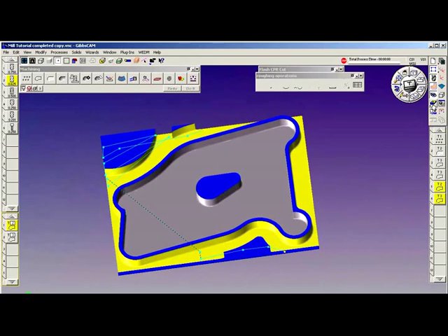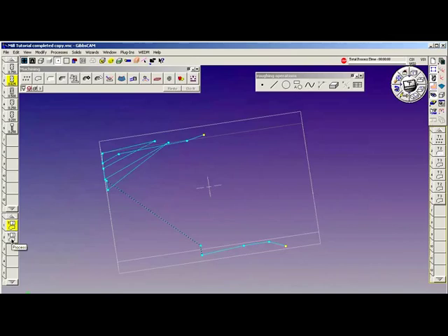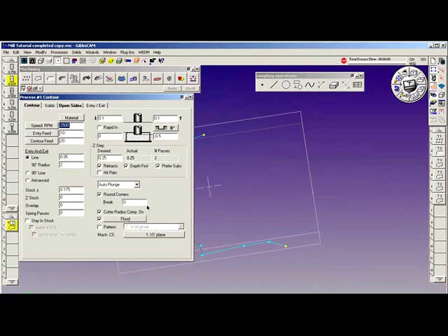So turn off rendering, deselect the operations, and I'm going to leave tool number 2 where it is. And if I look at it, I'm going to leave the feeds and speeds alone, change my entry exit moves to 0 because I want to cut this on center line. My stock is going to be 0. Rapid approach is fine. Top of the cut, rapid retract, depth of cut, and we'll do it in 2 cuts, 0.25. All right. Close the dialog.